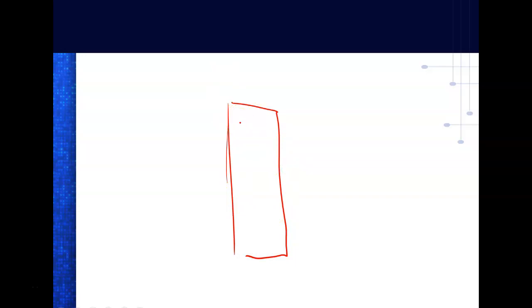The PLC has a common. If you look at the inputs across the top, you'll see DC common. Look at the top of the PLC. We have 2 DC commons. So what we can do on this PLC, we've got 2 groups that we can set up as sink or source. We're setting our inputs up as sinking, so that means my input devices have to be sourced. So we're taking that common.